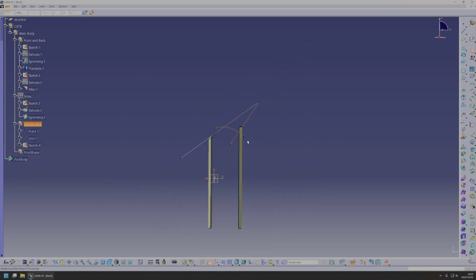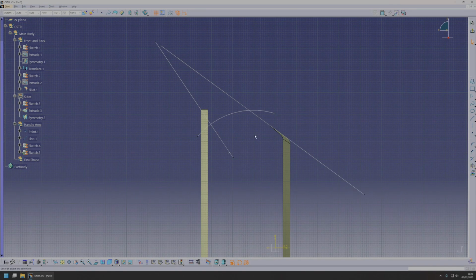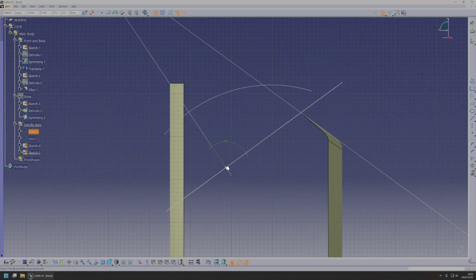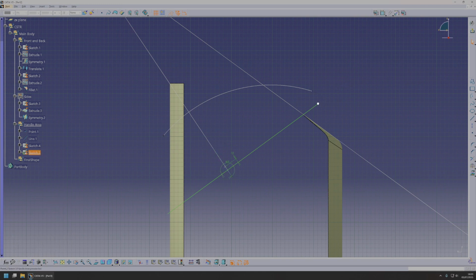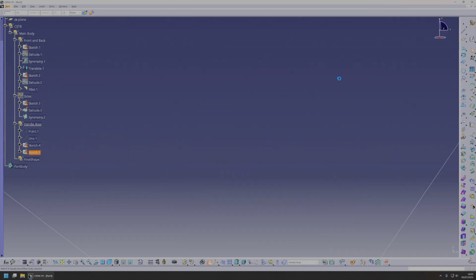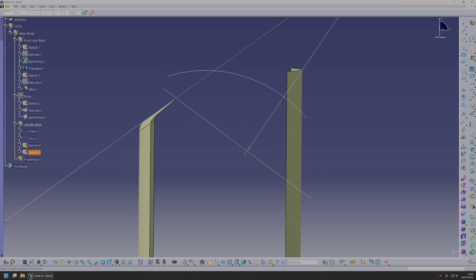Now we're gonna need to pick up a line basically where the handle surface starts. So we need to have something like this. This will be 90 degrees to this one, and it will be somewhere along these lines here. Maybe 5, maybe 10 millimeters. Right, I'm not really happy about this condition here, but let's see. Right, good. Now we're going to extrude this line